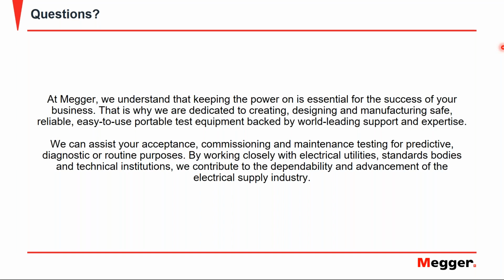So the only thing which you can do is compare phases with each other to look for some phase differences and then have the identification of a local defect instead of looking to the aging. So Tangens delta for high voltage cables as a detection of the aging, I would say for the time being is not possible or no information available, and it's also not known if it can be detected using a Tangens delta measurement.